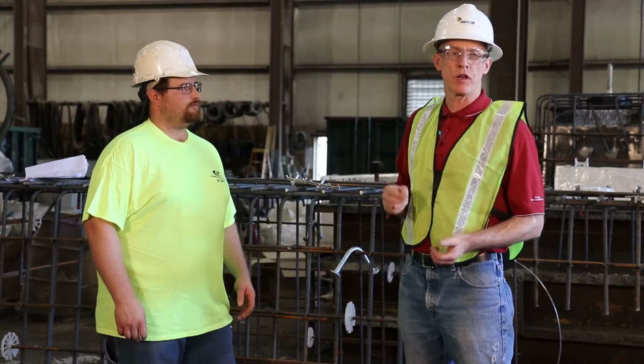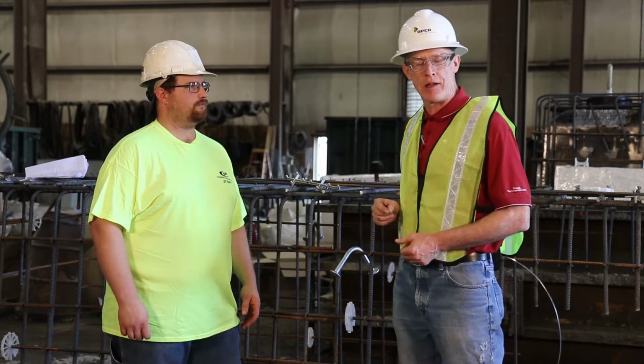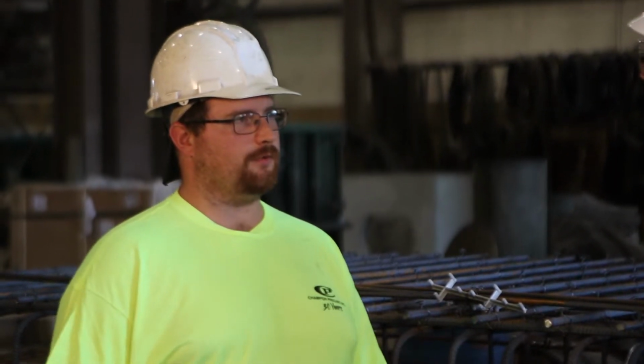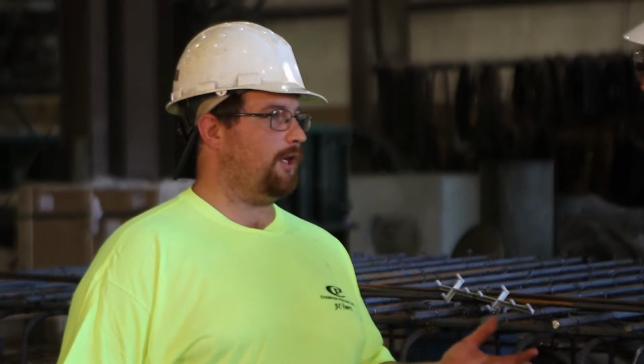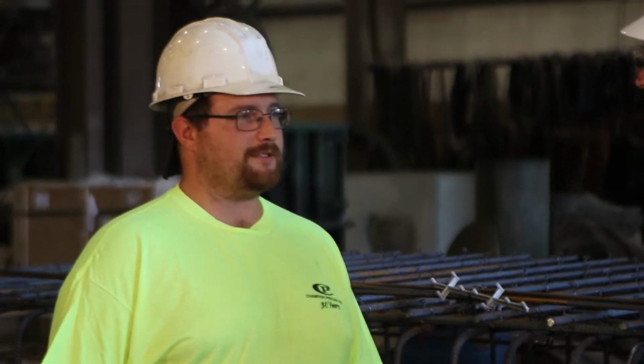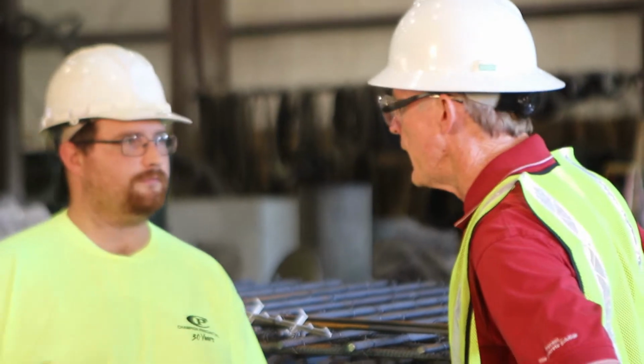Though it may seem logical that you could always substitute a larger bar for a smaller bar, some projects actually will prohibit it. Or other projects, you have to get written permission from the owner. So it's important to have a policy like Michael just described. Sometimes another type of substitution is whether welded wire reinforcement can be used instead of the required rebar. And just like the required rebar size, this also has to be approved by our QC department, and sometimes even the product engineer.